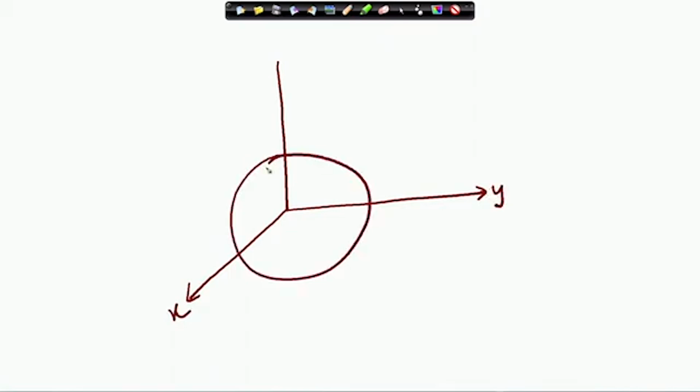This was the H plane pattern of a current element. Actually there is no maximum, or all points are maximum. So, there is no beam width, it cannot be defined here. If you have some variation, then only you can define beam width. So, this is the radiation pattern we have discussed.